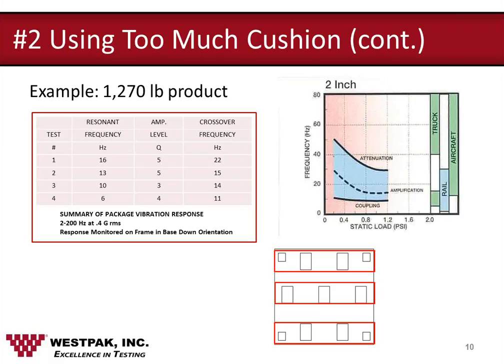So we've done several studies for customers where we've put what's called a saver unit inside their package or on a truck and recorded the distribution environment from different locations. So from like California back to Ohio and from California down to Mexico, and recorded the data, taken it, put it into our vibration controller and increased amplification, it looks very similar to the new ASTM truck profile and the ISTA 3A over-the-road profile.